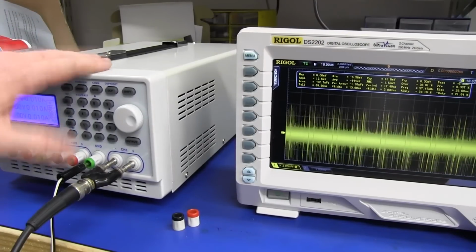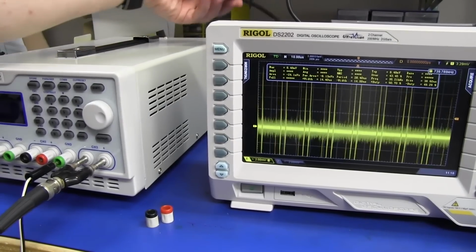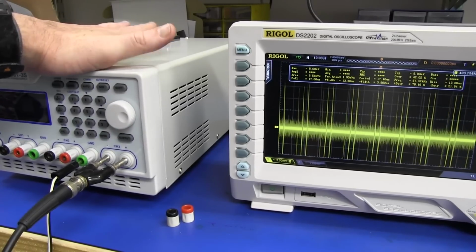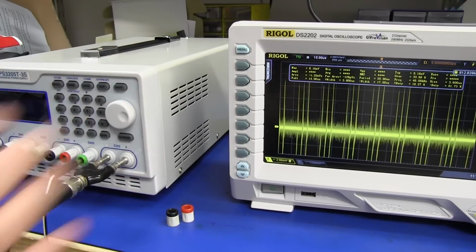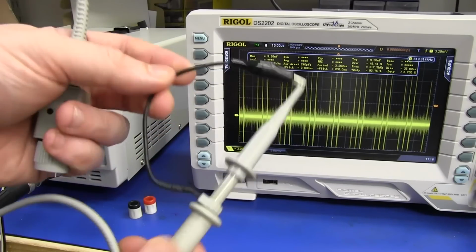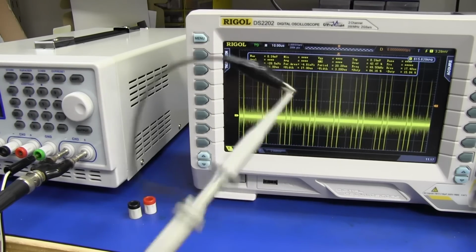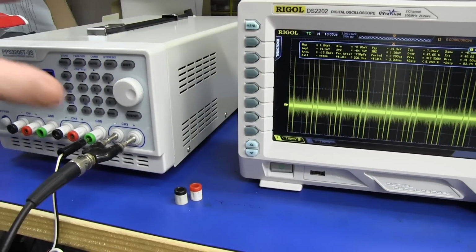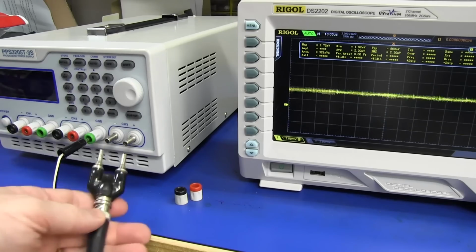So you might be asking, well, why was this thing picking it up even though it's switched off and disconnected from the mains like that? Well, it's because the internal circuitry and the internal transformer in here, via AC coupling, is effectively working as a very effective pickup antenna, so to speak. And that's why this oscilloscope probe won't pick it up, because this is a relatively high frequency pickup coil, okay? It's going to pick up ESD and lots of high frequency discharges and stuff like that, as I've shown in previous videos. So the transformer inside here and the coupling to it is basically going to work as a better lower frequency pickup antenna for that stuff. That's why if we disconnect it, bingo, we're gone, okay?